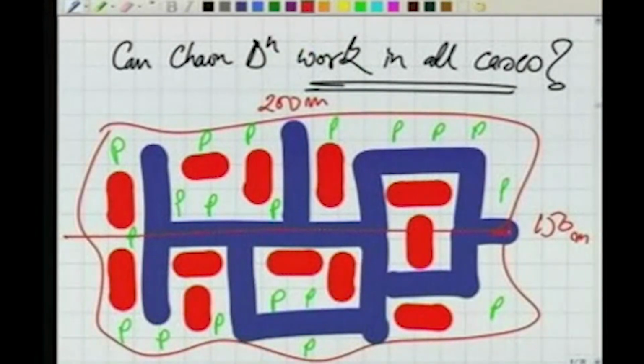Can we really make the triangles? Before we go for the triangulation, let us say we are using a single chain here. In this area, if I put my single chain somewhere here, my station A and station B, we cannot do the surveying using a single chain. Number one, the offsets are very long. This is 150 meter, of the order of 75 meter.